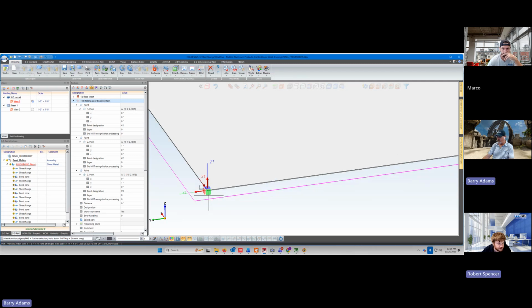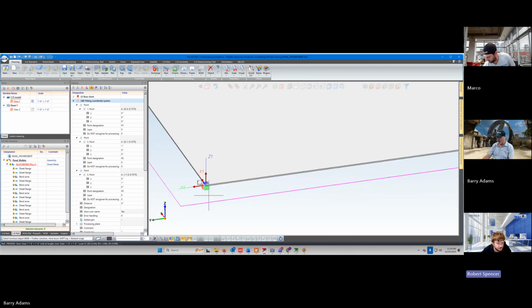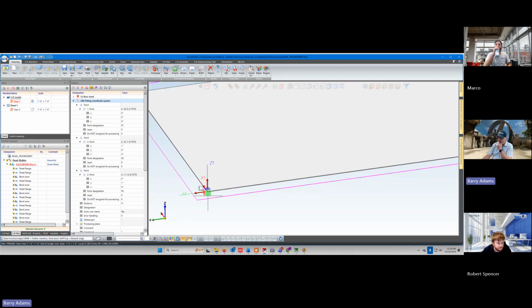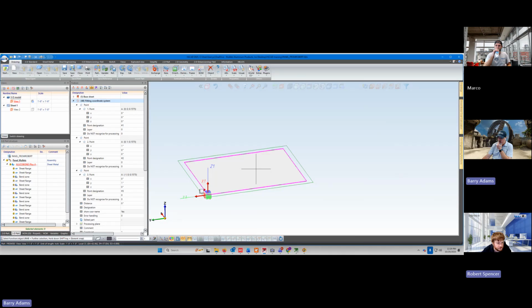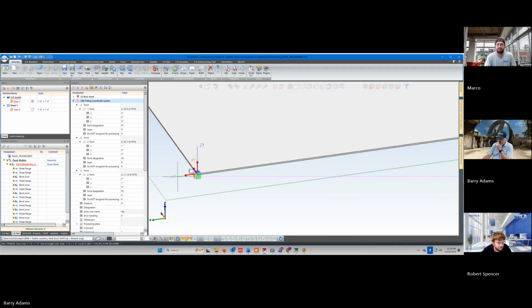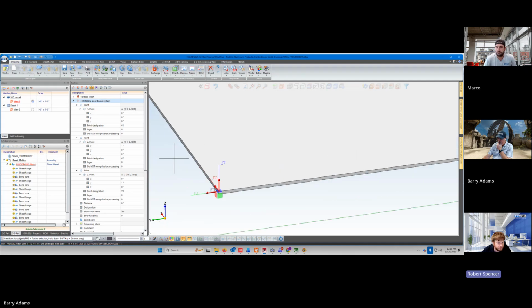Yeah. The processing plane does not have the X going left to right and the Y going bottom to top. So it's now matching the processing plane, but I should have started on this corner over here. Well, no, let's see, to put it bluntly, just pay attention to the direction of your processing plane. Don't just slap it on there. You know, dance your cursor around until it's going the way you want it.